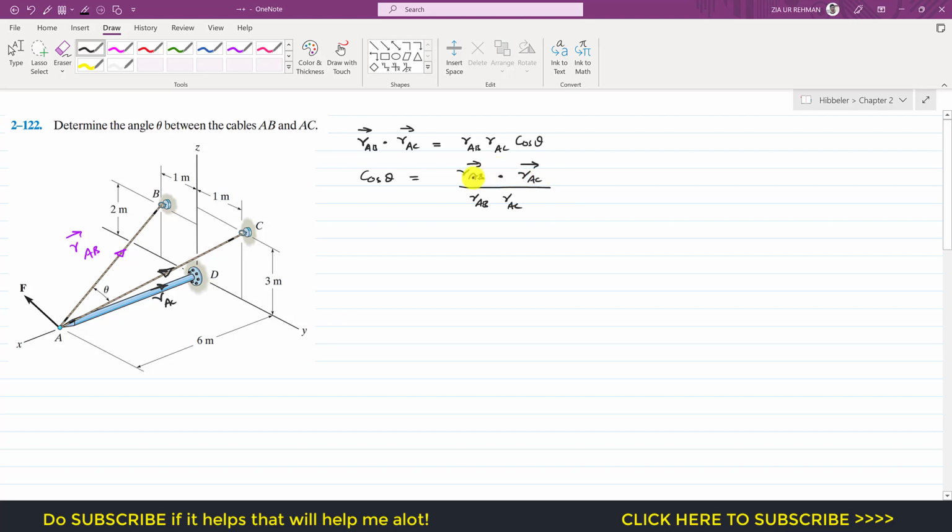So now to solve this problem, we need to find the position vector from A to B and the position vector from A to C. The position vector from A to B, we can find by traveling from point A along the x, y and z axes until we reach point B. To reach point B from A, we need to move 6 meters in the negative x direction, so I will write minus 6i.